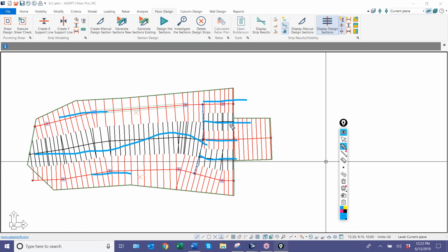I don't think it's incorrect. It's just you could take this slab and break it up into 1 foot design strips and get basically a unit strip along both directions if you wanted to lay your rebar out in that fashion. So all that's happening is you're displacing some of this tributary in this box and this box. So you're going to get localized reinforcement when we process this in those two zones.